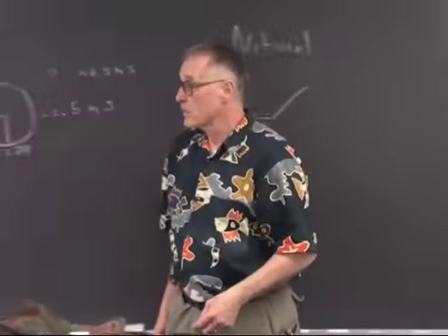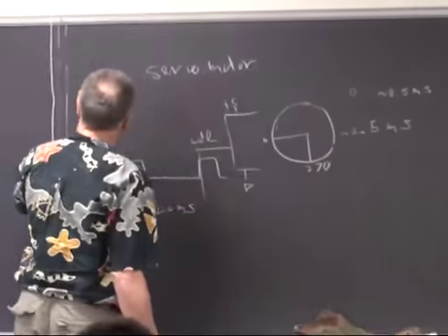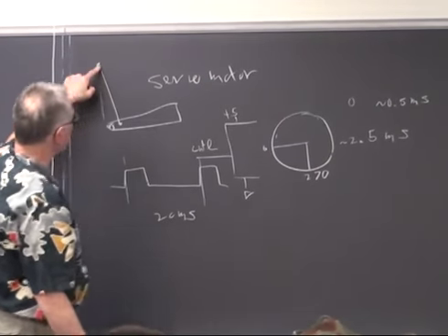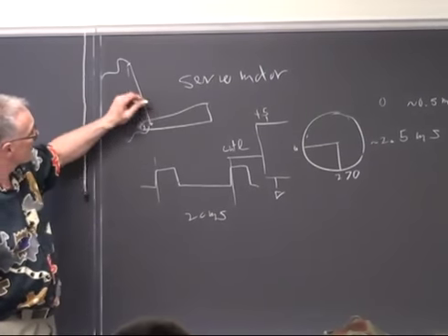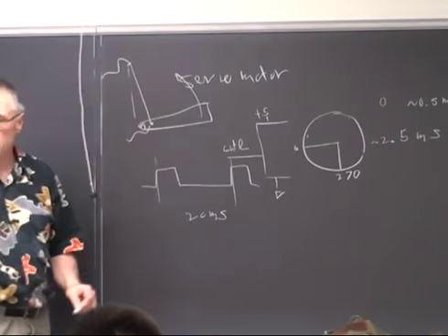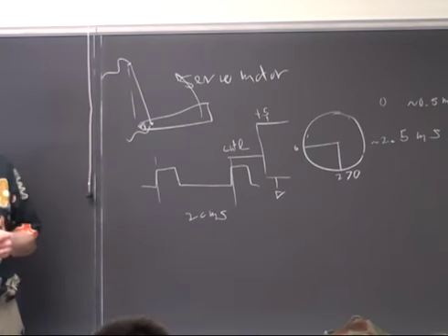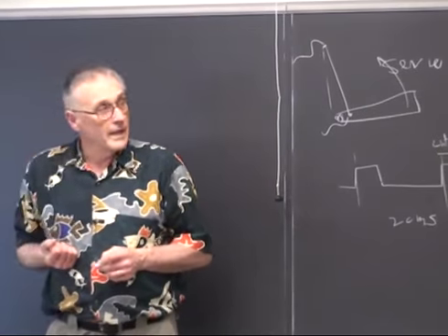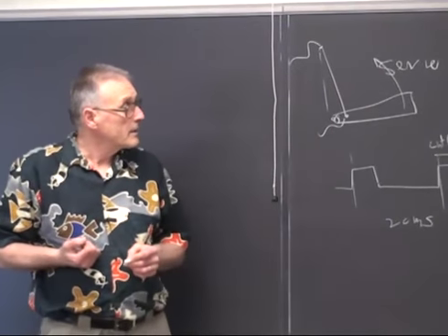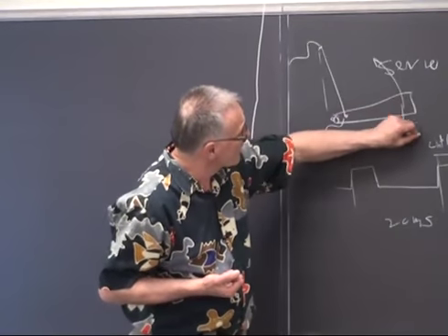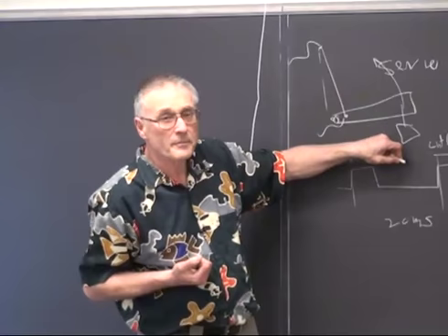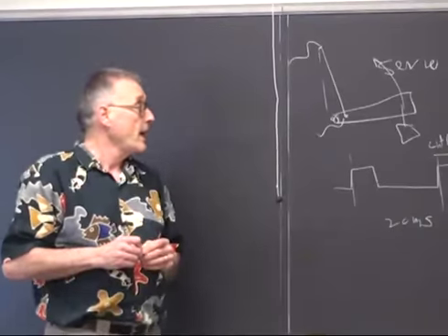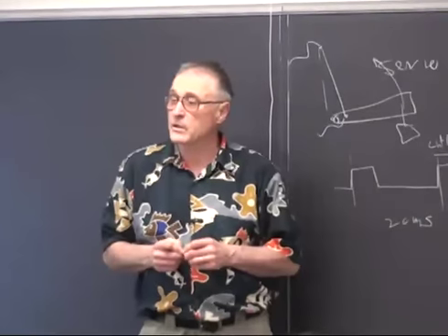Because the force is so great on a nitinol wire, you can make a thing that looks an awful lot like a limb with the wire attached up here. You put some current through this wire, it shortens 5%, and this moves up, just like your forearm. The advantage of it is it's completely quiet. It produces no sound at all. And it's reversible. You have to have some weight on here so that when you turn the current off, the arm comes back down again. It's reversible over several thousand actuations at least. And the forces are quite large.